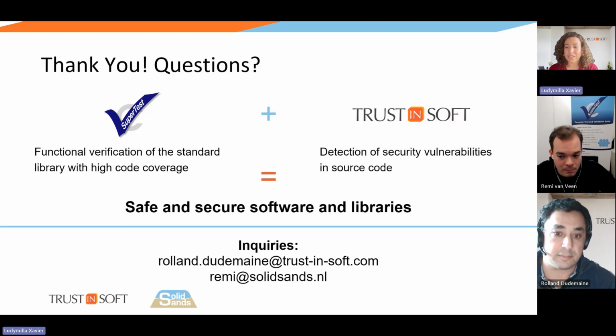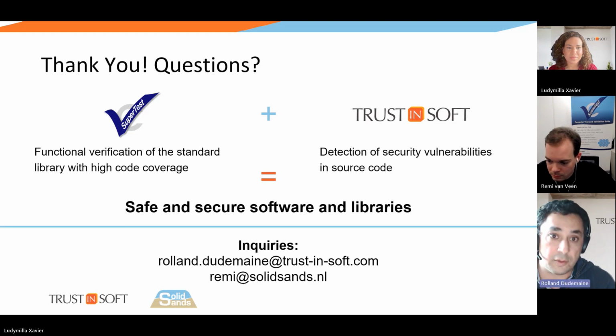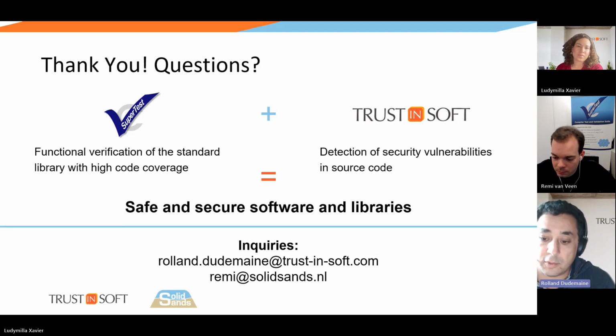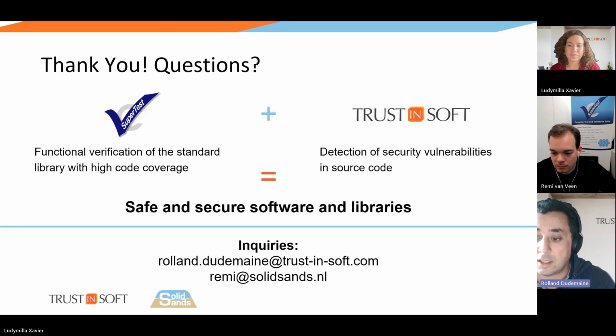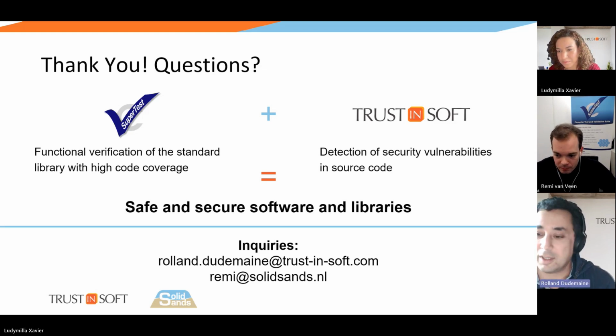We have a second question about the code coverage. Does it also include MCDC coverage? Also, does the tool help find the adequate values to reach the missing coverage, or only provide the lines and branches? So this analyzer, and that's part of the safety qualified part of the tool, does provide line, statement, function, branch and MCDC coverage. So that's the full scale of it.